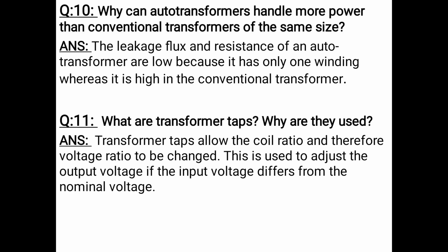Number 11. What are transformer taps? Why are they used? Answer. Transformer taps allow the coil ratio and therefore the voltage ratio to be changed. This is used to adjust the output voltage when the input voltage differs from the normal voltage.